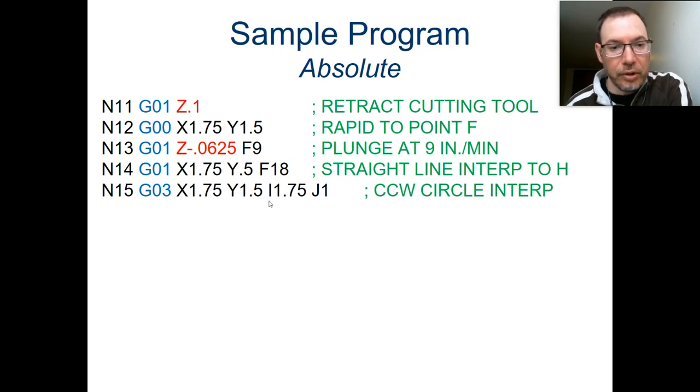And so they're using the center point method here. If you remember when we did center point, we use I and J for your X and your Y for center point because we can't use X and Y, since we're already using those for the end point. So they've used I and J. And if we were using a Z, we'd use K as the coordinate for the Z. We aren't going to actually need that one, but that's what we'd use.